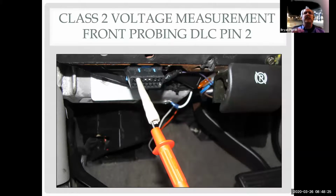So we used an adapter here because they didn't have a breakout box like we have at the school. They use an adapter here, which is a small spade connector that goes in and then has a test connector in the back to put the meter on. You never want to take your meter and shove that round meter into where that spade goes, because you'll open the pins up and then the scan tool won't work. So it's real important to do that properly.